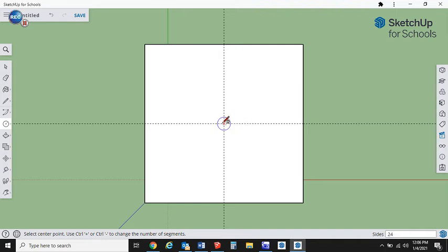And we're going to click on that intersection, drag, click, release, drag, and we're going to create a 2 millimeter circle, 2 millimeter radius of a circle. So 2, enter, and remember, radius is from the center of the circle to the outside. Diameter would be from one side of the circle to the other side. So this would be a 4 millimeter diameter or 2 millimeter radius circle, and that's what all these are going to be.